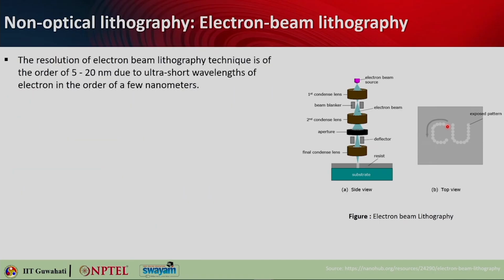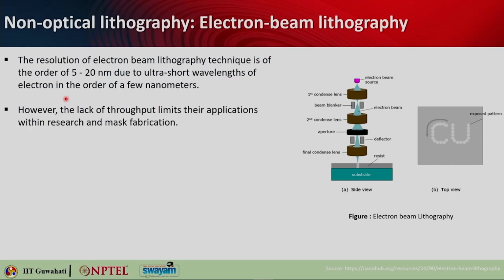Here the resolution is of great importance. As you can see, the resolution of e-beam lithography is of the order of 5 to 20 nanometers, due to the ultra short wavelength of the electron, which is in the order of a few nanometers. However, the lack of throughput limits its applications to research and mask fabrication.